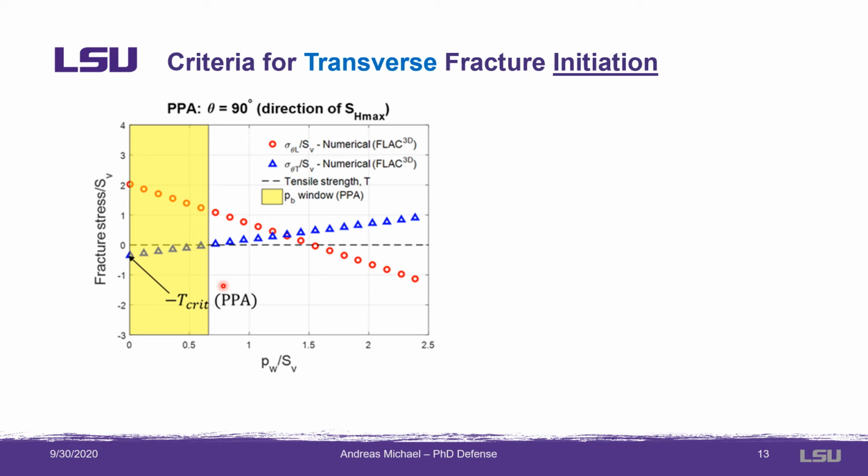Varying the perforation direction makes these two constraints vary as well. Using this diagram, you can also read the fracture initiation pressure from the x-axis, which is the wellbore pressure at which the corresponding stress line crosses the black dotted line, which indicates the rock's tensile strength, again assumed to be 0. One extreme perforation direction is aligned with the smaller of the two stresses orthogonal to the wellbore, yielding the highest value of these two constraints.